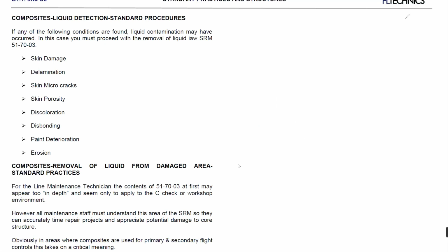And when you're doing a walk around, especially the flight crew, they see the dent, the circle, it's written okay, and they think that someone already investigated this damage, okay, assessed the damage, everything is fine. But nobody is checking the book, if it's in the book.